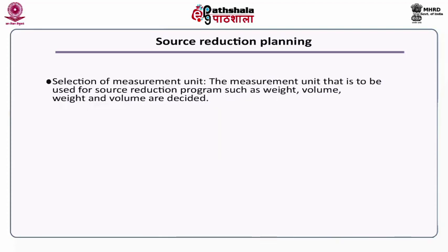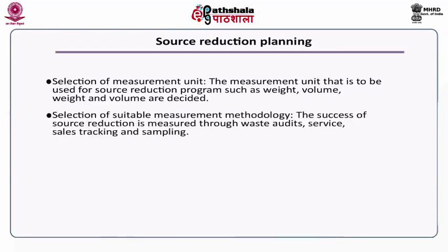The third step would be to select the measurement unit. How are you going to measure the source reduction progress? So, the measurement unit that is to be used for the source reduction program, like the weight or volume, should be decided and mentioned before. Selection of a suitable measurement methodology: what is the method that you are going to use for measuring the progress? The success of a source reduction is measured through waste audits, surveys, sales tracking and sampling.